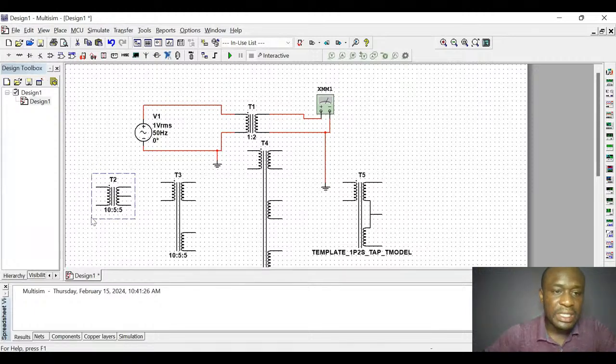Depending on the voltage level you want to moderate, let's assume that we are using 220 volts or 240 volts for all our appliances in the house, but what the utility company is supplying to your house at the time is 180 volts, and your freezer or your television cannot operate. You have to buy a stabilizer for it. Inside that stabilizer, there is an auto transformer, and that auto transformer is designed in